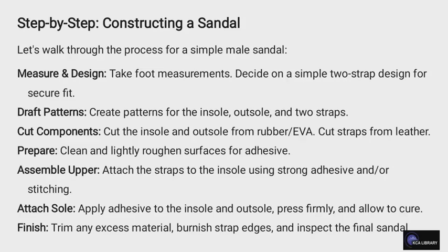Talking about the steps in constructing a sandal, we talk about measuring and design, which we've talked about. We talk about drafting of pattern, cutting of components like cutting of insole and outsole from rubber, cutting of straps from leather, and also the preparation, which is cleaning and roughing surfaces for adhesive.